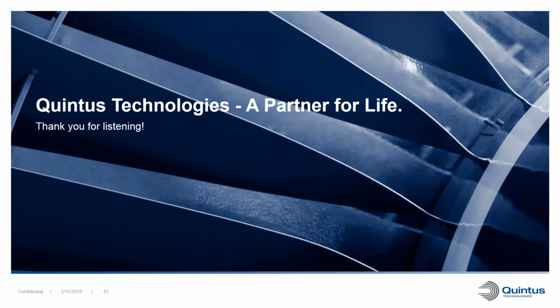Our first question is from Nigel. Nigel says, is it possible to HIP detailed or intricate parts manufactured via additive manufacturing rather than simpler or basic shapes? I can answer that. Yes, that is possible. There is no limitation on how complex the geometry is. You can HIP any kind of part with any kind of geometry, as long as the geometry will fit in the HIP furnace.